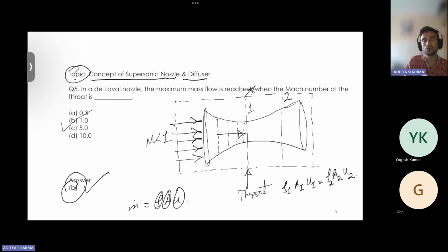So as this velocity reaches a point where the Mach of the flow is 1, it's not possible for the flow, in terms of its potential, to further accelerate on decreasing the area of this convergent duct, all right?